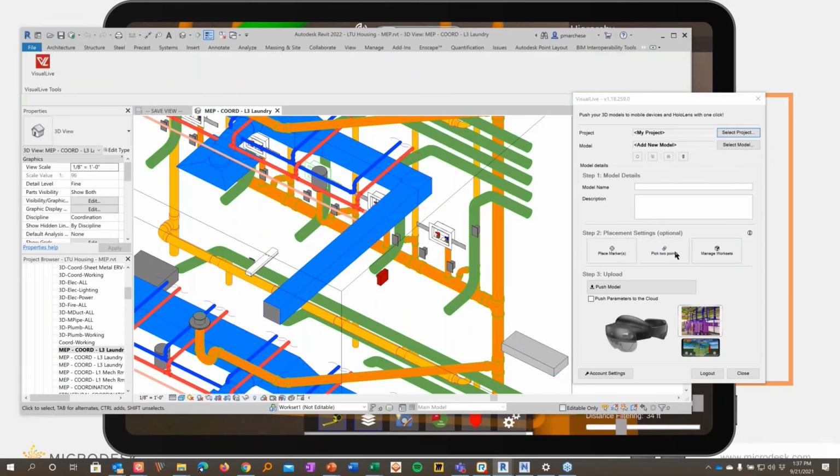And then I can also choose to pick 2 points. So like if I'm at a staircase, or I'm at a door frame, or I'm at a column grid intersection, this allows me to say I want to place point 1 here, point 2 there. And it would basically be, 1 there, 2. I go out into the field and I pick those 2 points in my model. I pick the 2 points in the real world, and that helps align everything to that.